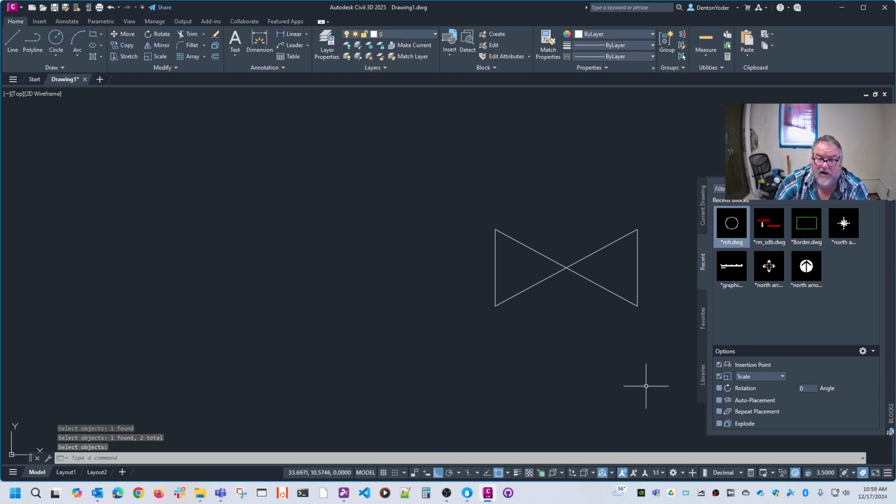Okay. Do I want to make it a ball valve? Sure. There's a command called donut. If I set the inside diameter to 0 and the outside diameter to about like that, I can put a little donut in, and I like to draw a little line that comes up and tees over a little bit to make a handle to turn the valve, and I'm going to call that a ball valve. So W for W block,